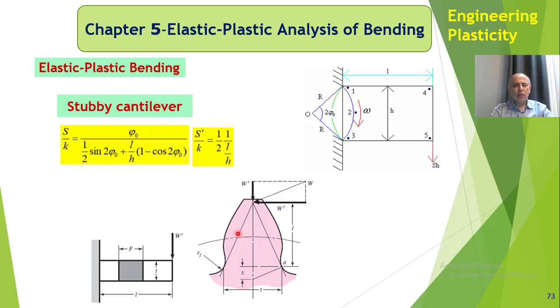In order to get the bending moment relationships for the tooth design, we compared it to a cantilever beam. In fact, Lewis did this, Lewis method. Lewis compared it to a cantilever beam, and using the cantilever geometry, Lewis obtained a relationship for the bending moment.